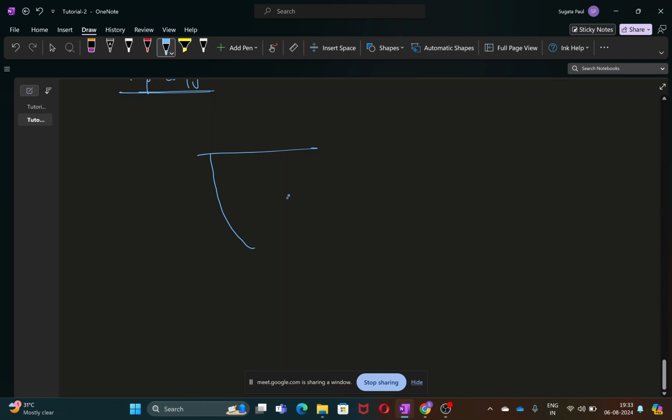I am making a double wall dewar, but there can be multiple walls present, to isolate the liquid helium from the environment so that it does not evaporate through heat exchange. So the dewar should be properly insulated with multiple walls. This is a dewar flask in which there is liquid helium, and this is the liquid helium level and bath, at the helium liquid temperature, which is 4 Kelvin initially.